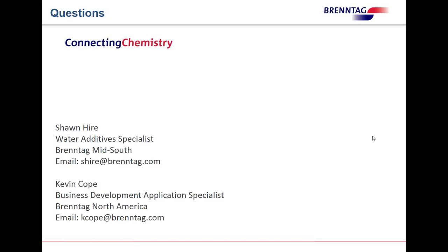Iron also acts as an excellent sludge conditioner when people are dewatering. I think it's favored if, in the biosolids, like if people are making Class A biosolids, iron is probably preferable. Whereas alum doesn't really help with conditioning of sludge. But alum will also run through your system and not cause any issues with UV, or even with struvite formation. That can happen because of iron in the system.